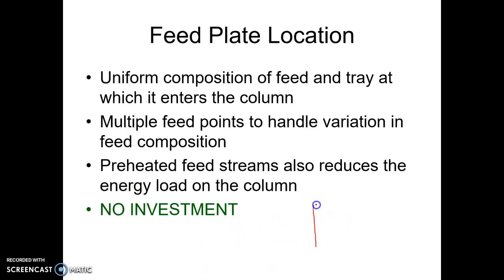This is a distillation column. This is your actual feed, like a single design feed. But let's say the composition may vary. So you can provide two additional feed locations, and there could be a valve which can be operated depending upon the feed composition.